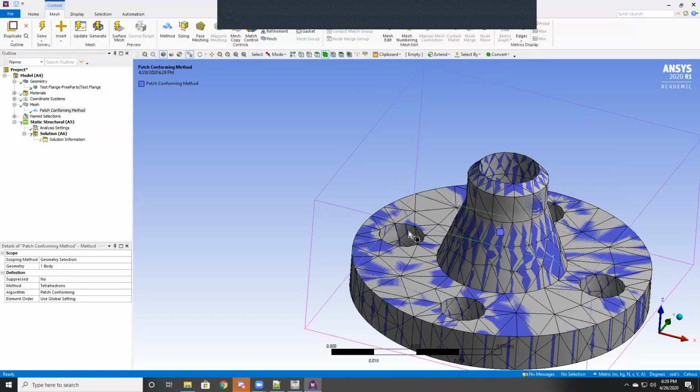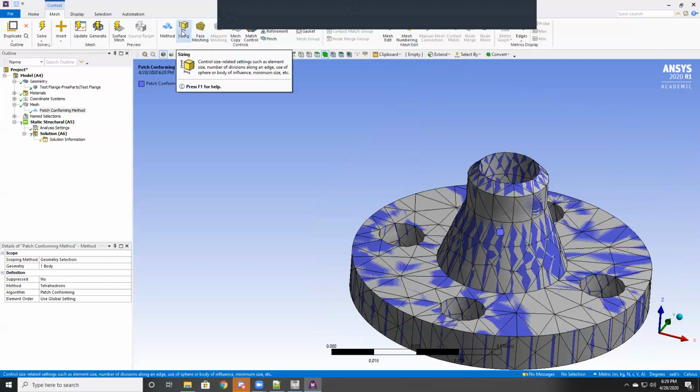However, refinements tend to make for worse quality and skewness because when you apply them, they result in a lot of smaller cells transitioning to larger cells, which is messing with your skewness. And some of the cells to fit into that boundary where they merge together are very low quality. So ideally, you only use a refinement if the geometry of the mesh is not matching the geometry of your system. In this case, we're not too concerned right now. The better effect for reducing skewness and improving quality is a sizing.